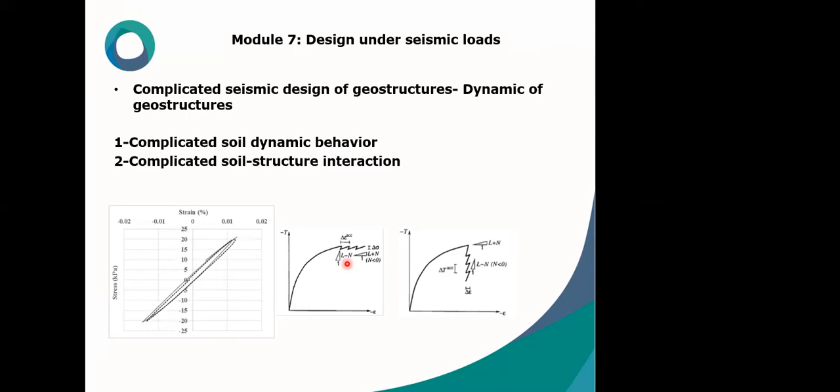And the ratcheting, what's ratcheting? Let me explain a little about the ratcheting. At the smallest strain ranges, granular soil has incrementally nonlinear behavior with a high stiffness that gradually decreases with increasing deviator stress. A soil model should be able to predict higher initial stiffness after reloading. If not, ratcheting is eliminated. It means cumulative strain during cycles causes ratcheting, and it should be considered in the soil models.